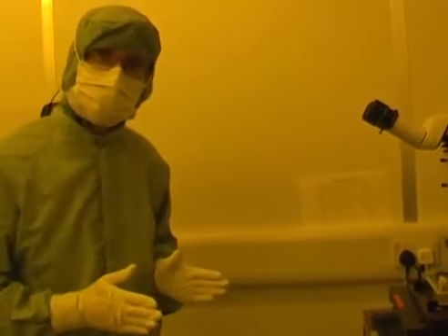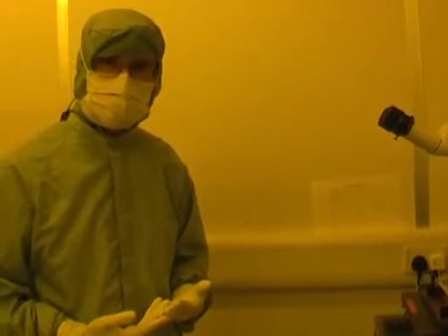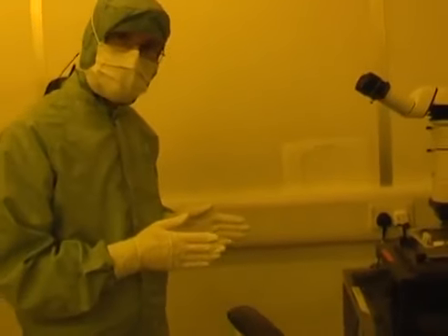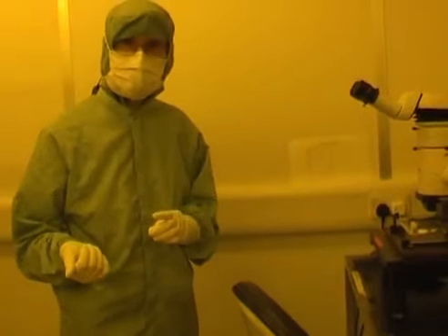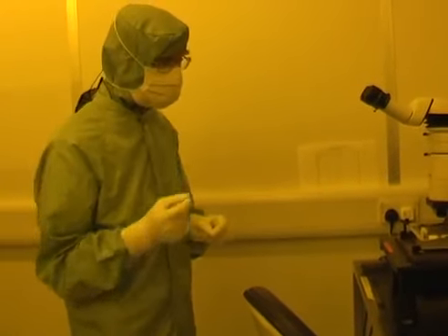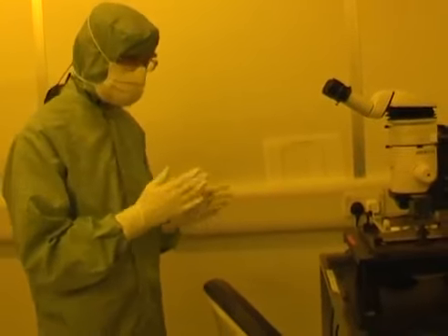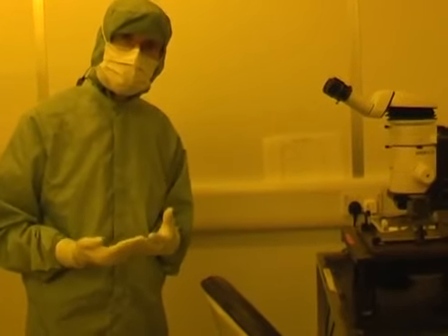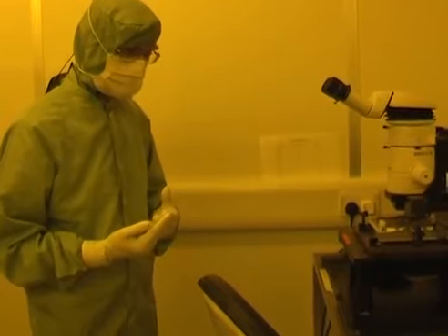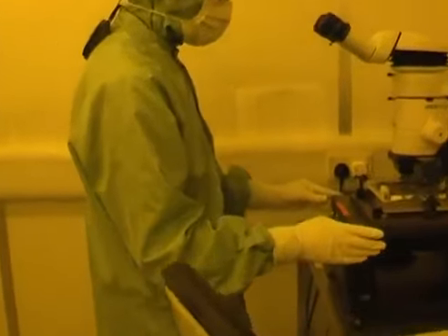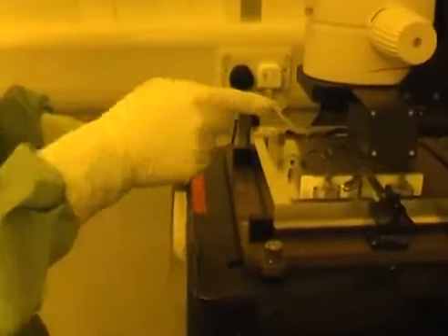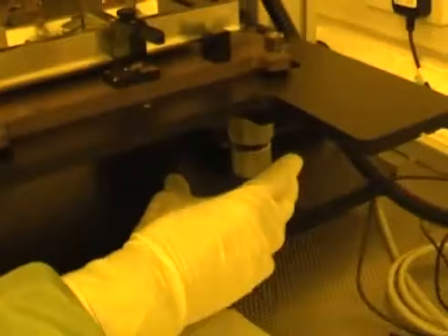So the sample's on the holder. The height's been adjusted as well as I can. The alignment's been done. The last thing before I mount it into the machine is that I need to locate exactly where it is. So when I put it into the VB6 and find it using the electron beam, I know where I'm going. So I'm going to do that by measuring the distance from the Faraday cup to the sample. So the Faraday cup is that hole there, and the idea is that we make sure that the XY position is centered.